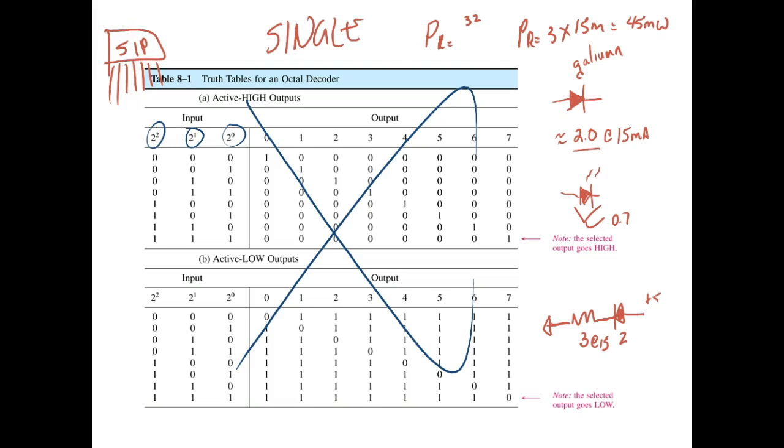You'll see a lot of these, and what they'll do is they'll come over here. If they're pull-up resistors, inside all the resistors will be done like this, and then they'll come over here and bring a pin out. So all these pins right here would be what a pull-up resistor would do, right? You understand? So these are SIPs. You'll see a lot of SIPs on digital circuits. These are going to be just pull-up resistors, and they occupy little space, right?